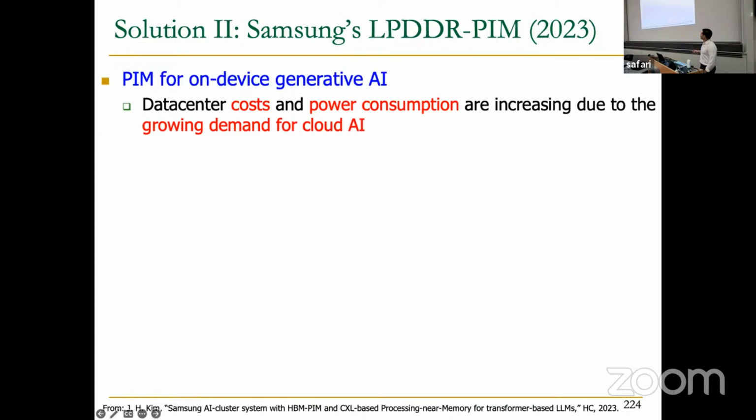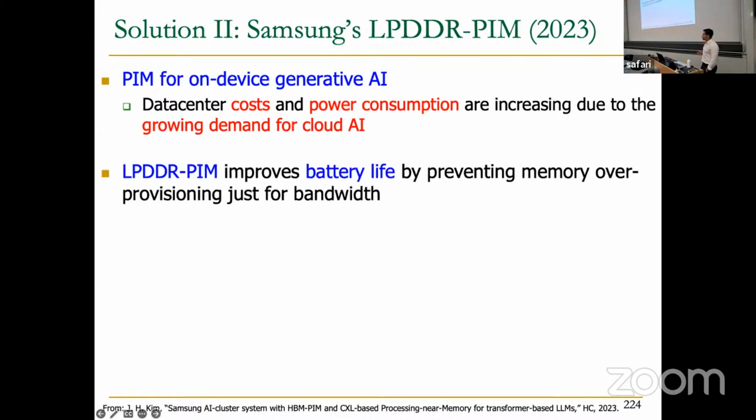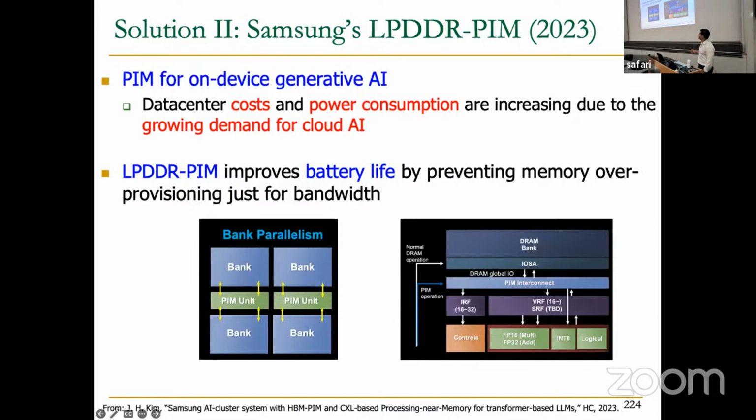So they also have implementations of similar architectures for mobile devices, generative AI on edge devices. And here they are not going to use the HBM chips anymore, because you don't embed HBM chips on small form factor SoCs like a phone, but they are going to use low power DDR4X memory devices that target those architectures.